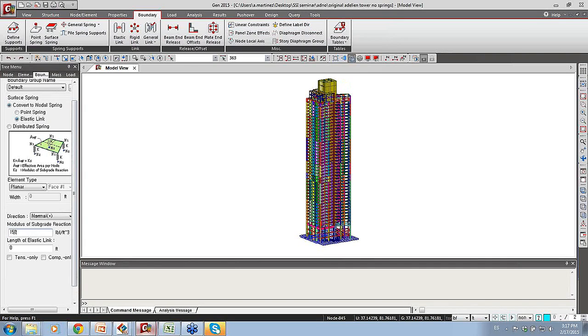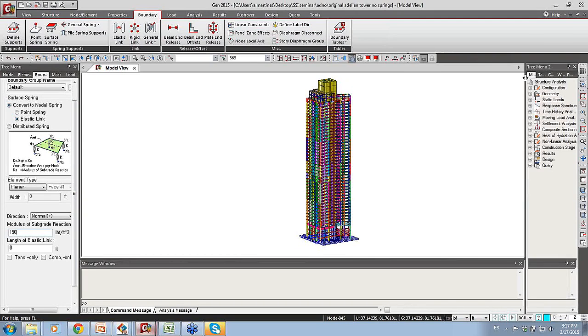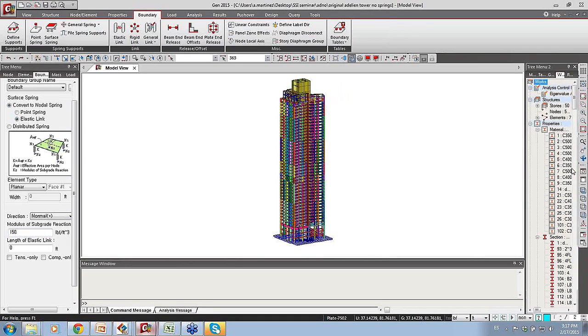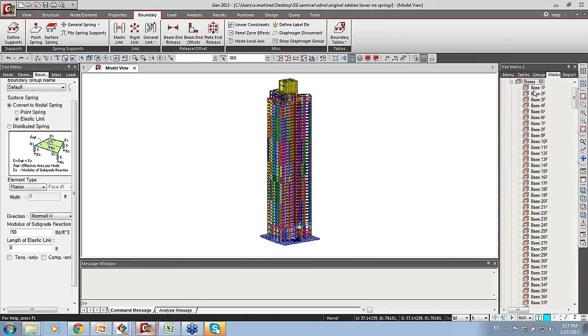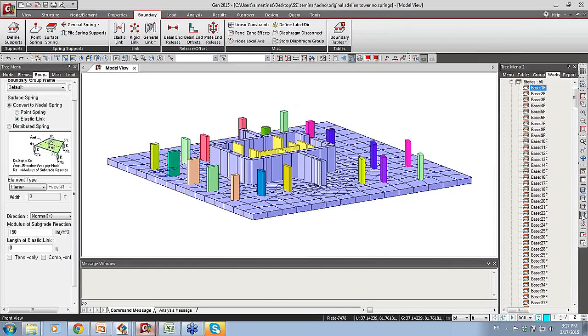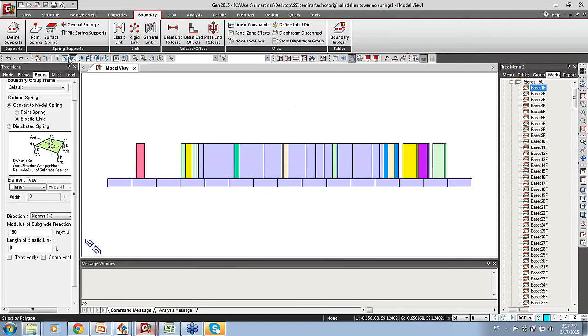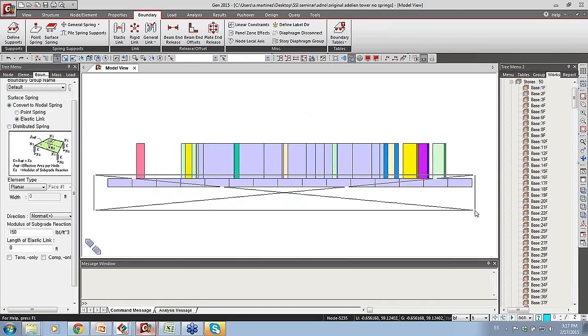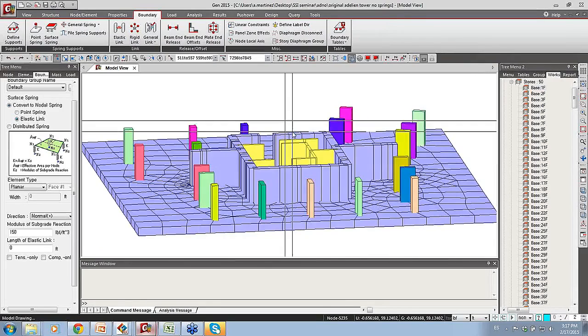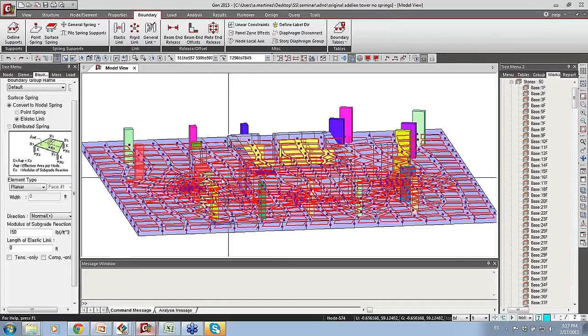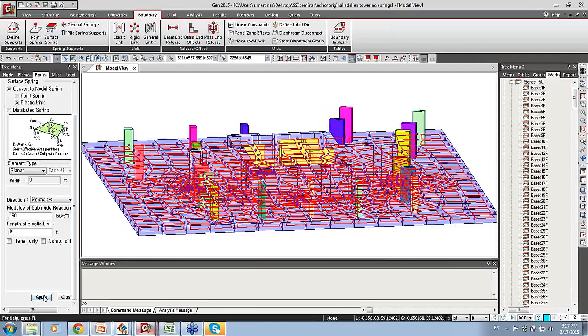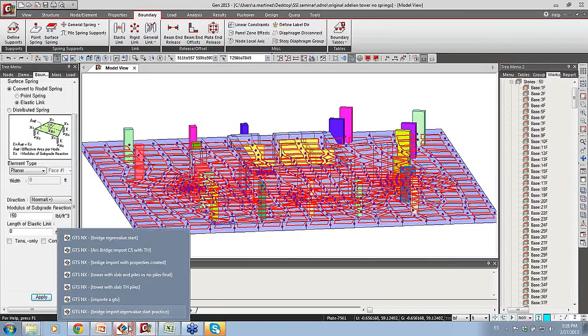Let's just do this. I'm going to activate my structure now by floor. I could do it by section, I could do it by material, I can do it by stories. So I can just say here, activate only the first story. It's a little easier for me to handle. I can do the side view, and then here I can just select, create a box around the nodes. We see here that the nodes of the raft have been activated, and I can just apply them directly if I want them to be tension only or compression only. And then I could just run this analysis again.